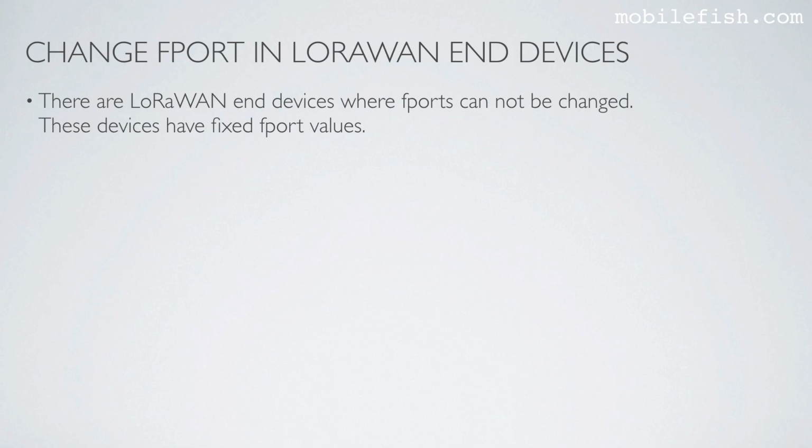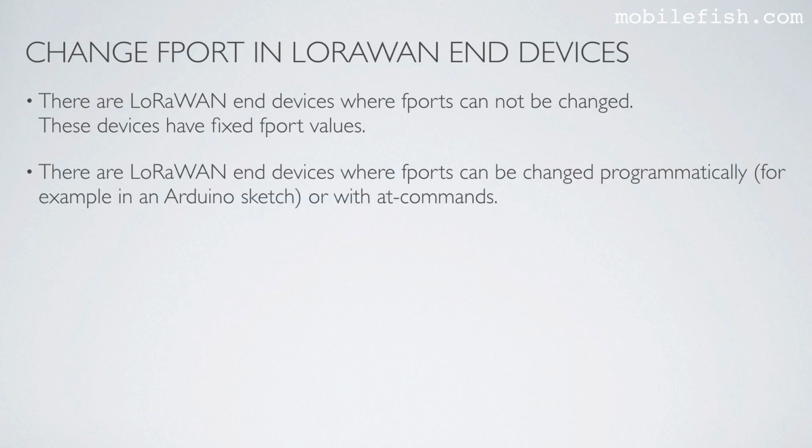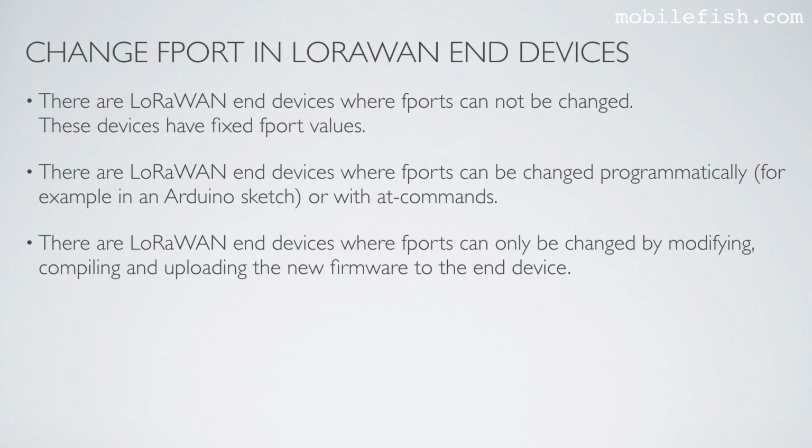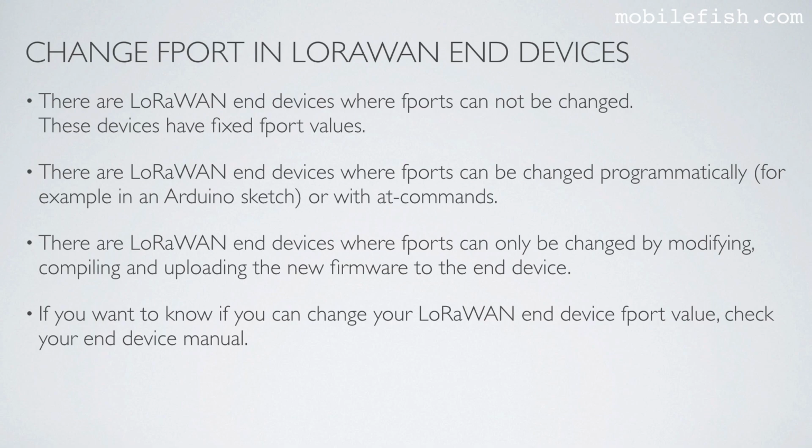There are LoRaWAN end devices where FPorts cannot be changed. These devices have fixed FPort values. There are LoRaWAN end devices where FPorts can be changed programmatically, for example in an Arduino sketch, or with AT commands. There are LoRaWAN end devices where FPorts can only be changed by modifying, compiling, and uploading the new firmware to the end device. If you want to know if you can change your LoRaWAN end device FPort value, check